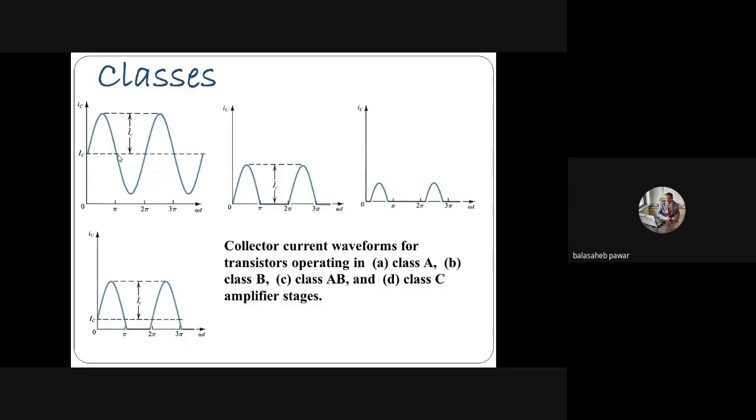And quiescent collector current means what? It is a DC component, right? So at pi or 2 pi, as the output coupling capacitor is connected in series with the load and the collector terminal or the drain terminal of BJT or MOSFET respectively, that coupling capacitor blocks the DC component and hence the output is 0. But later on, that component again becomes time varying. So that capacitor again provides the output. That's why we are getting that output somewhat like an AC signal.